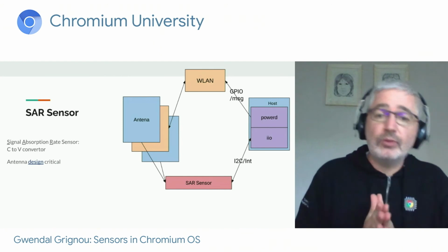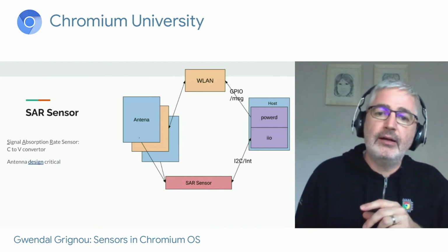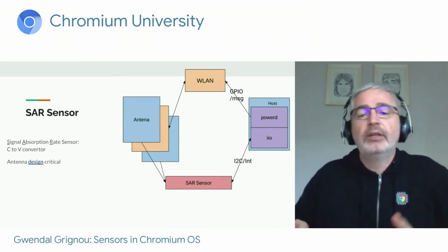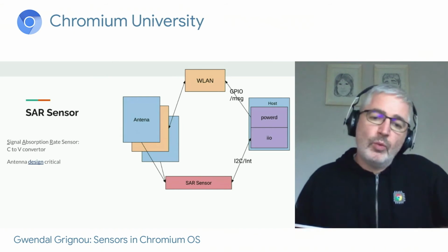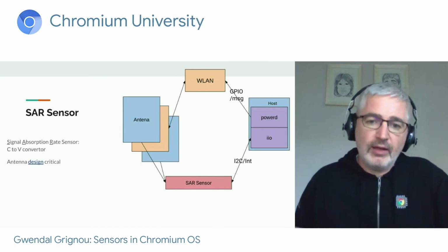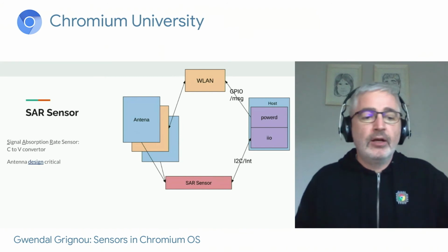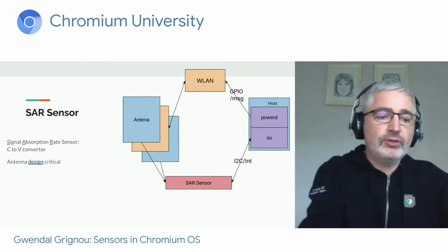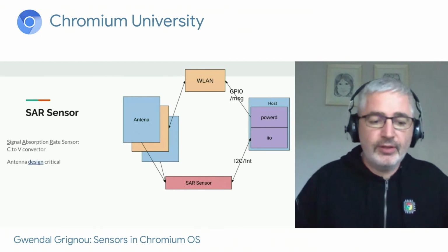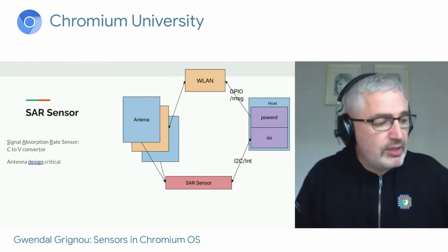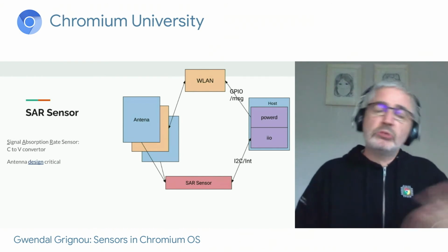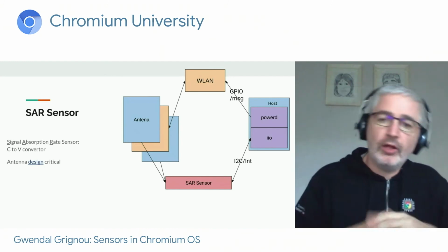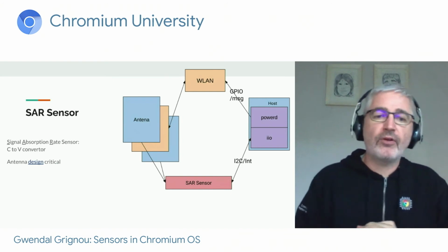It's actually not trivial. The antenna design has to be done in such a way that when you approach the antenna, we lower the power before you are actually on the antenna itself. Also, we have to tell the difference between someone holding the tablet and the tablet sitting on a table, which also changes the capacitance. But after configuration and initialization, when we are not debugging, we are just waiting for events.